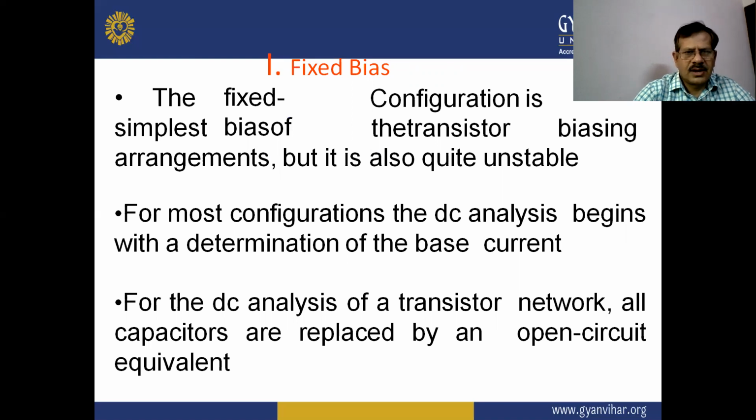For the DC analysis of a transistor network, all capacitors are replaced by an open circuit equivalent.